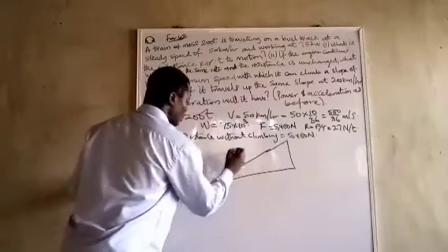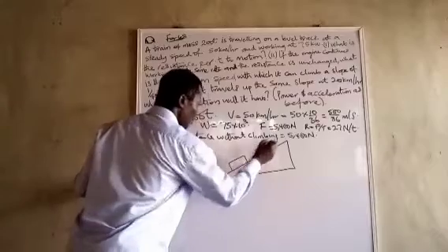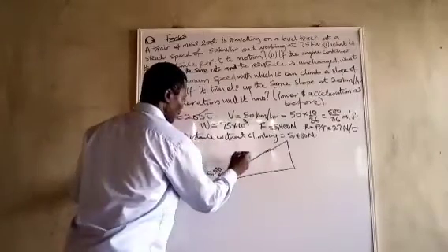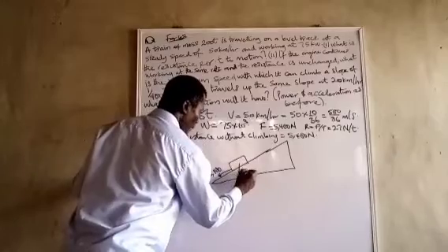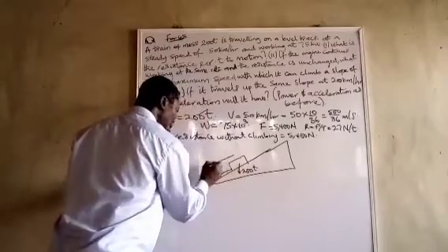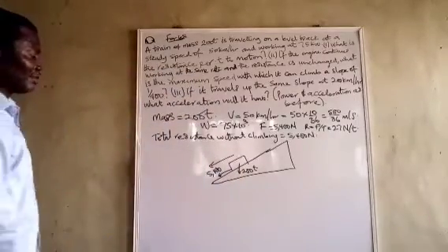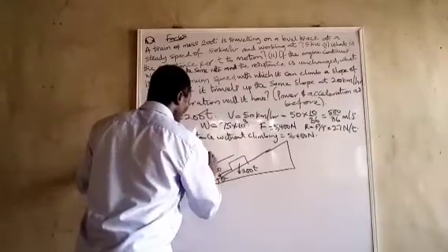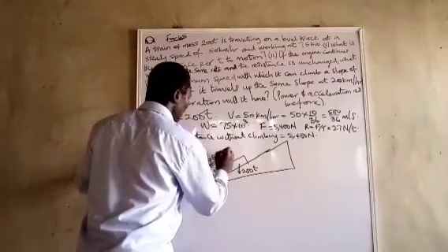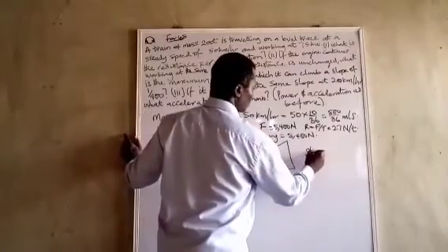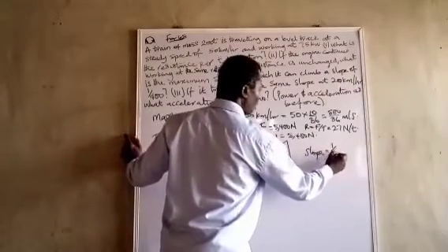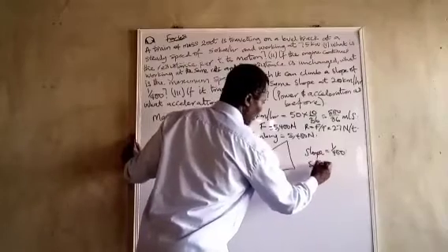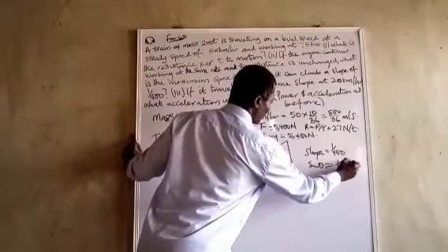So, the total resistance now will be this 5,400, plus additional resistance due to the weight's component downward, and that will be mg sine theta. We are told that the slope is equal to 1 over 400, so we can take this as our sine theta. So sine theta is 1 over 400.